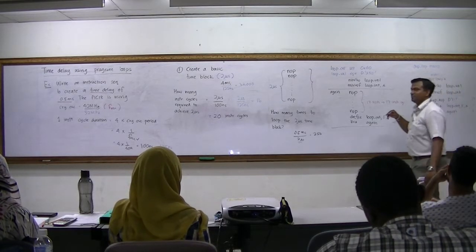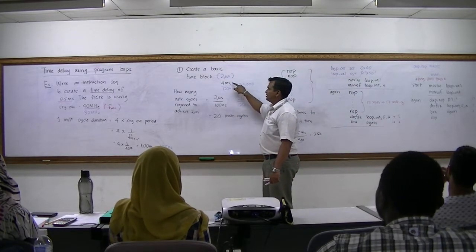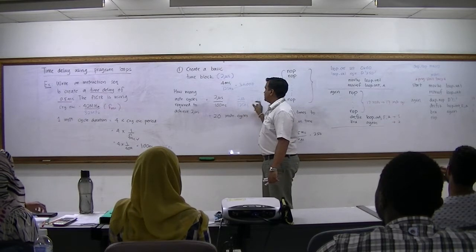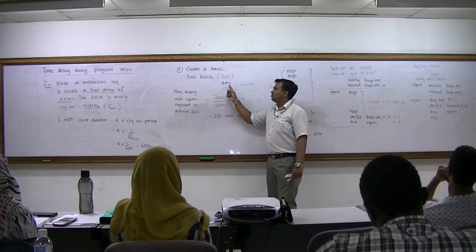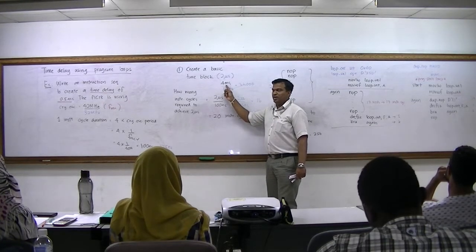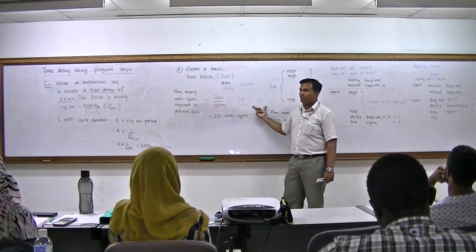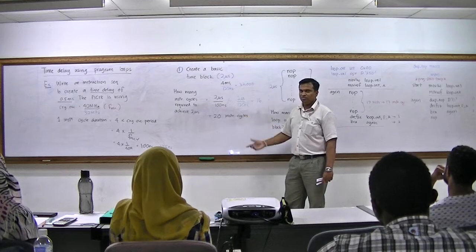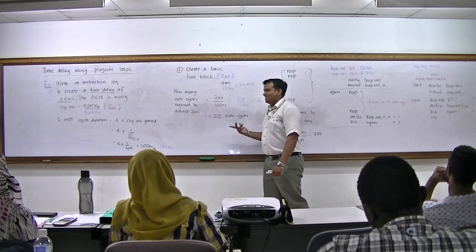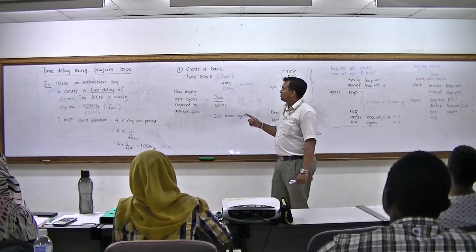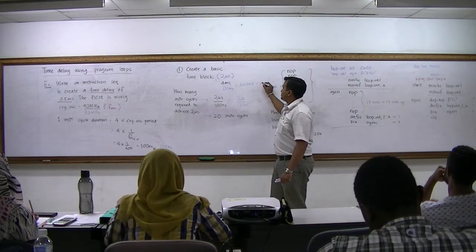So that's why we need to choose a smaller base value. The rule is you must choose a base value such that when you divide with the one instruction clock cycle, you get a value which is less than 255. That is the rule. Of course, later we'll see an easier shortcut, cheating. We'll see that. You understand? So that's why this one cannot, because this is more than 255.